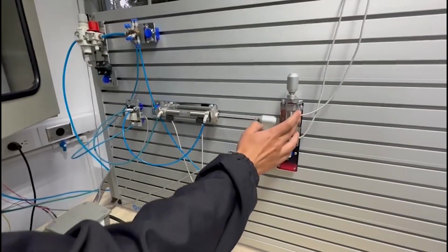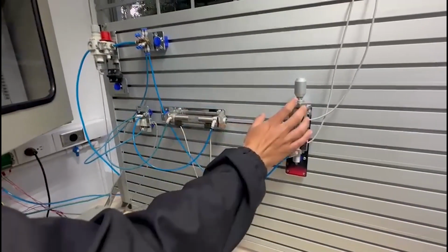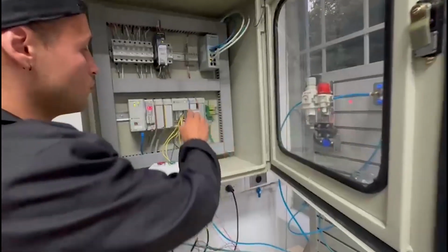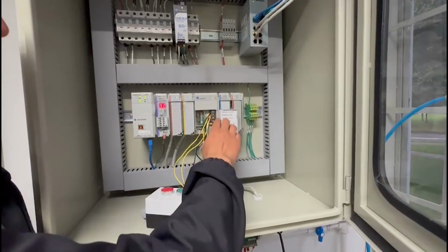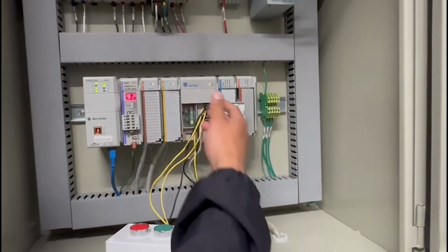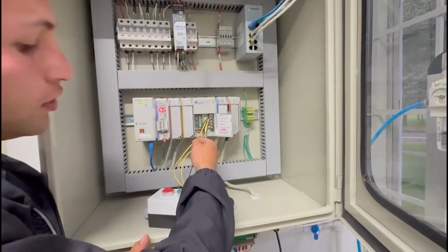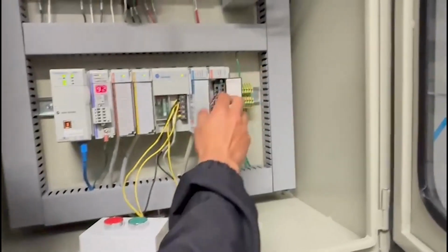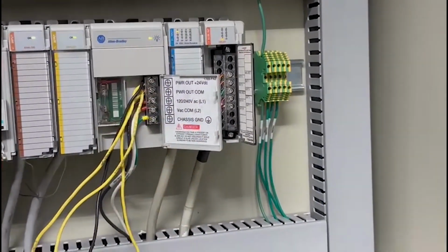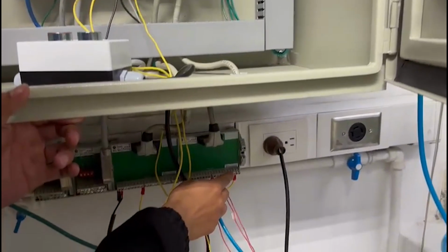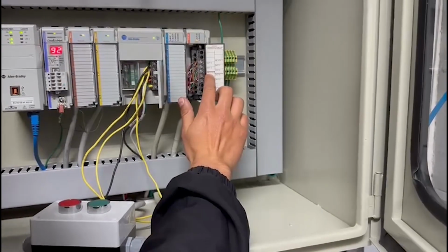There are three relays, and we have the source from the PLC, from Allen-Bradley, with a converter that gives you the option to get 24 VDC. Then we have to connect this 24 VDC to our digital output relay. So we get the power here, take it out, and connect it to the digital input of the relays for the power.